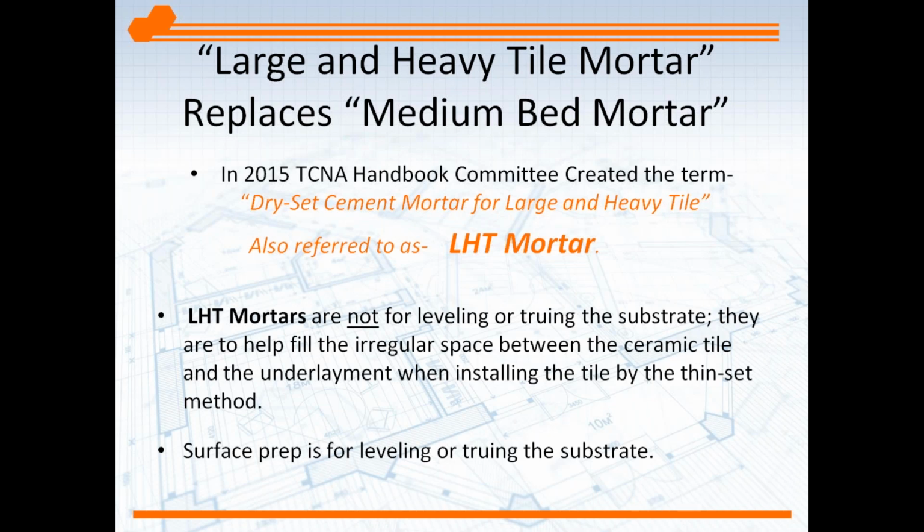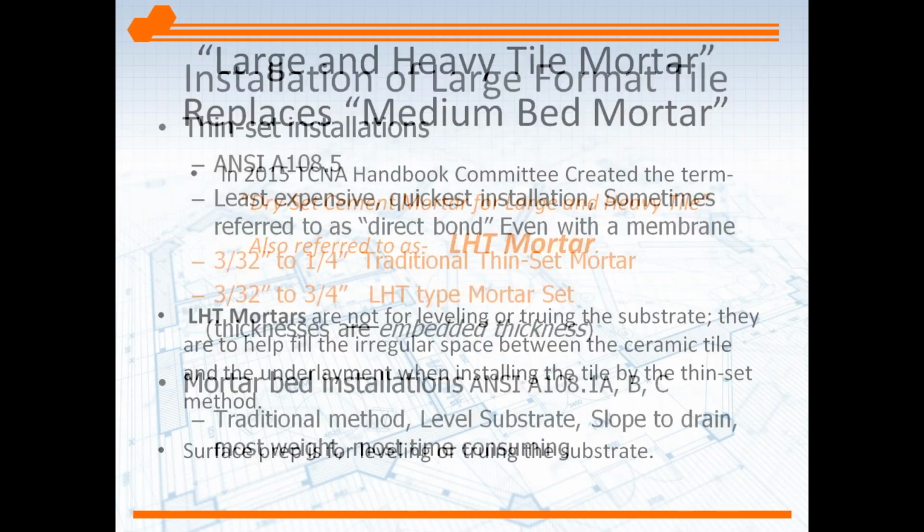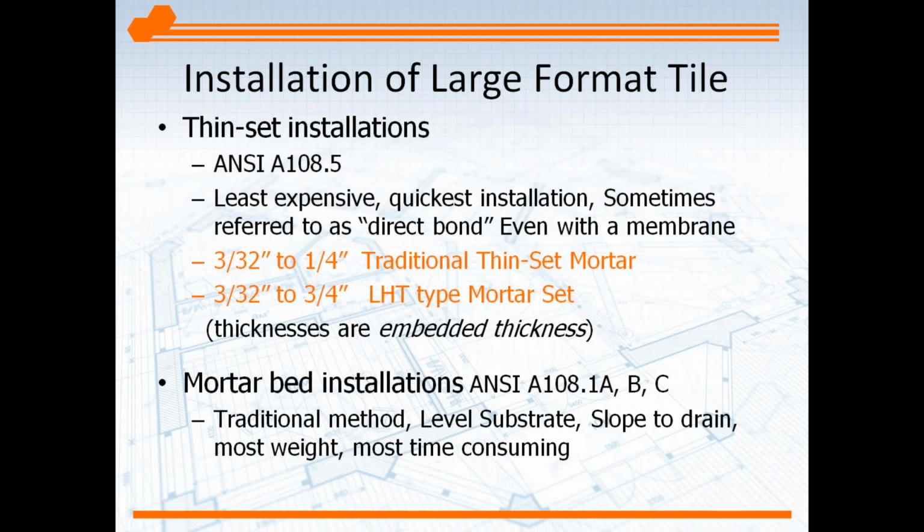So again, below that, we have the paragraph that says you're not supposed to true the surface up with these mortars. You're supposed to use a patching material, as I mentioned before. But these mortars are able to go in thicker. And why is that important? Well, as the tile becomes larger, it's more difficult to avoid lippage. Lippage means one tile is higher than the next. You need those tiles to be even with each other to avoid a lip of one tile sticking up higher than the other, causing all kinds of problems, tripping, damage to the tile.